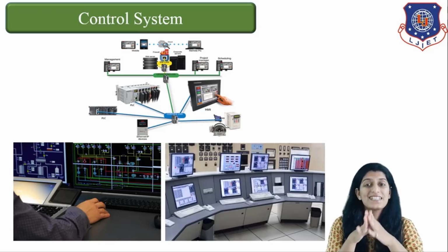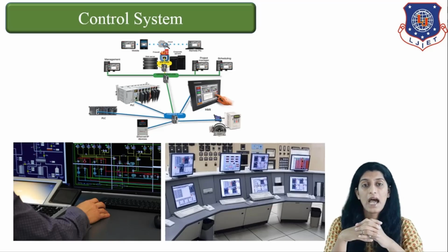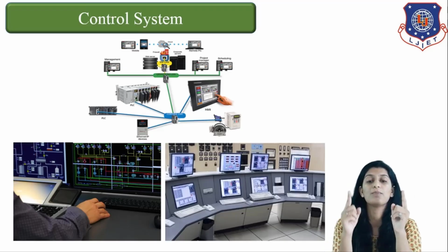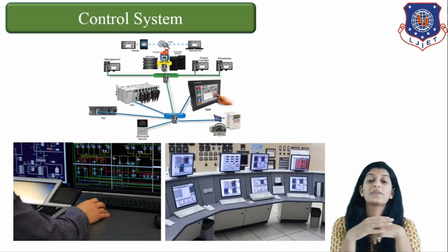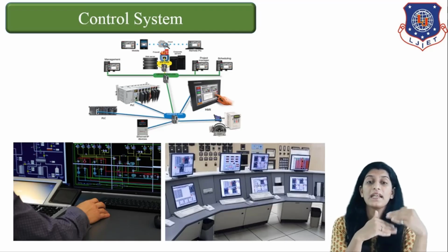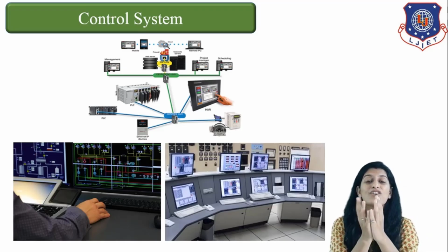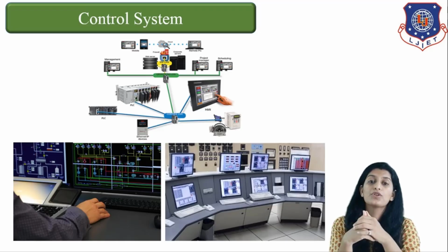Correct? So, for this purpose we are trying to determine the overall block diagram or overall transfer function of our given system. And for that we need to reduce our entire system to a single block. Right? So, the different loops which are present in our system need to be eliminated one by one, and we need to convert the entire complex block diagram into the simplest form.